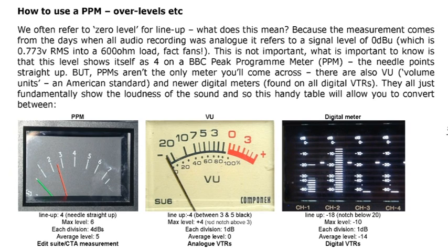It shows us the numbers that are stored on the digital tape. You can see there's a marker at the -20 position, and then another marker at the -10. And in Europe, by common consensus, our line-up tone will be put at -18 dBFS. That meter uses a measurement system called dBFS, which is very common.